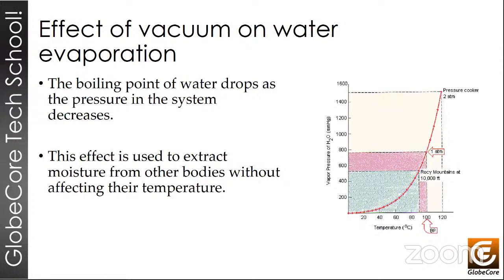So, the thermal vacuum process is a very common, very straightforward method of drying transformers due to the high efficiency and lack of any consumables in this process, no absorbents or anything like that. The thermal vacuum process uses the physical characteristics of water just to extract it from the oil.